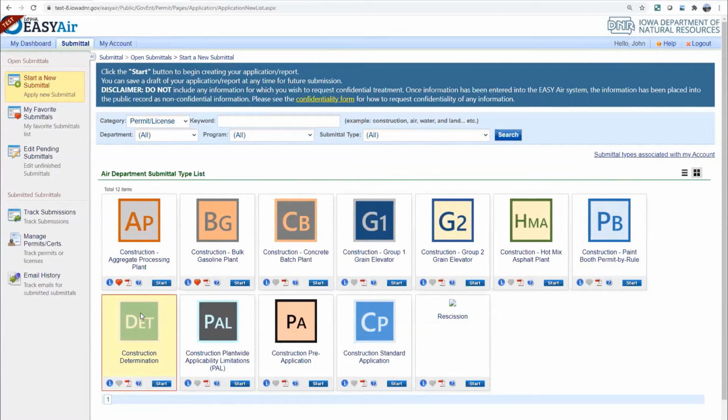Normally we're permitting by emission point. Each stack is going to get its own permit. But for these general permits, we're looking at the entire facility. You get one permit for the entire facility. This is an option. If you don't want to get a permit template, or what we also call a general permit, or if you don't meet the eligibility requirements, then you would use standard construction permits, and you would get individual permits for each emission point.